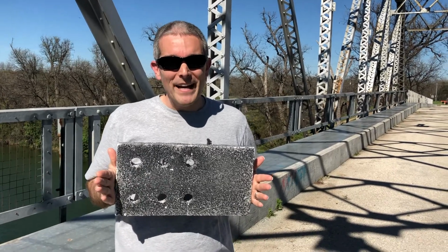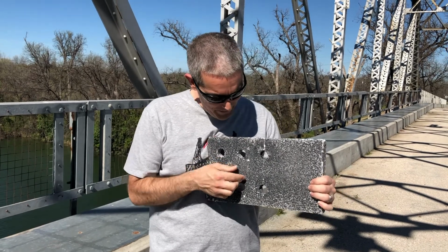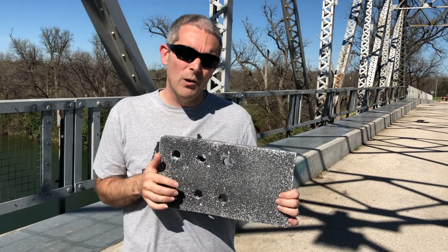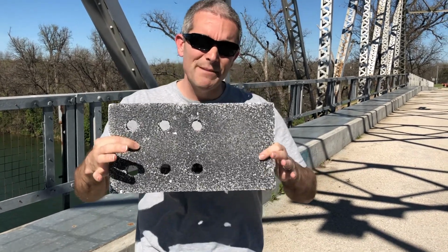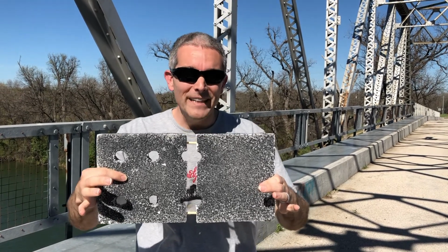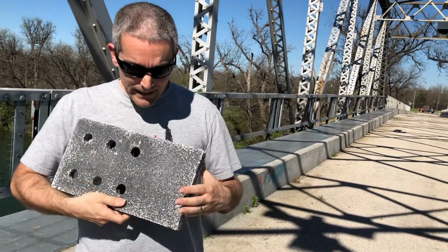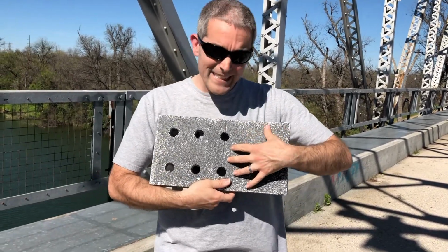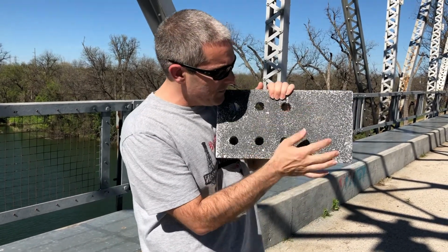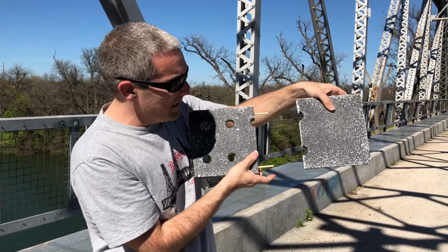All right, now that we've talked about yielding, we also have to consider fracture. So we said that fracture is probably going to happen where we have lower area or reduced cross-sectional area because of these bolt holes. So if I pull on this, what would you expect to happen? Hopefully you expected something like this to happen. You would see that we'd expect failure, and relative to where the force is, we will always expect failure at kind of the forward edge of the connection. So that's this first bolt line after the main member. And we would expect it to separate something like this.